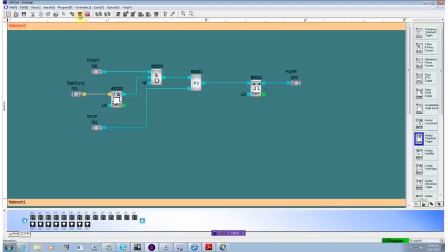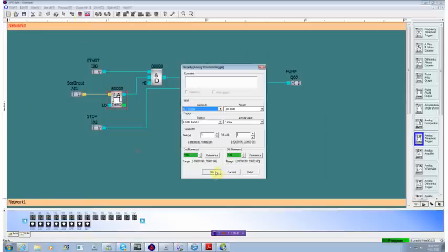Now when we start the simulation, we see that we have an on threshold and an off threshold. When we click on our analog input now, we have a slider, so we can actually set the analog value. As I slide the analog input up, once it hits a value of 5, the output came on. If I continue sliding it up, when it hits a value of 7.5, it turned it off. So that isn't exactly what we want, since we're looking at a resistance to ground, which is going to change voltage. Let's stop this and go back to these properties.